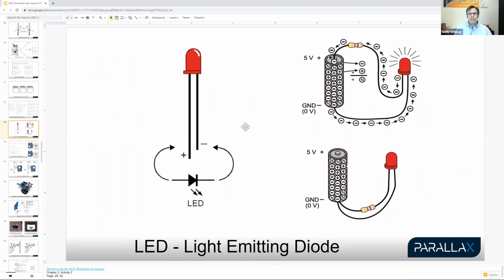All right, quick how it works. Back to the light emitting diode. To make a light go on, you have to give it some DC voltage, like connecting its ends to opposite ends of the battery, the plus and minus terminal. That forces current through. Whereas if you plugged both of them to the negative terminal of the battery, there's no voltage difference, so there's no pressure to push those electrons through, no current, no light.